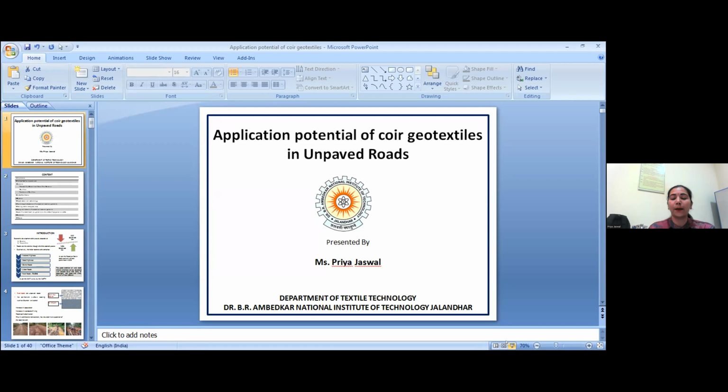So these are rural roads, but there are some problems faced by unpaved roads. These are loss of mechanical property with the constant passage of traffic due to extreme weather conditions, and along with time, the mechanical properties of the road get reduced due to increase of load. The whole structure loses its structural integrity, and subgrade softening also occurs, which results in poor drainage and rainwater infiltration. Since population is increasing, the soil left is not of high bearing capacity or adequate engineering property.